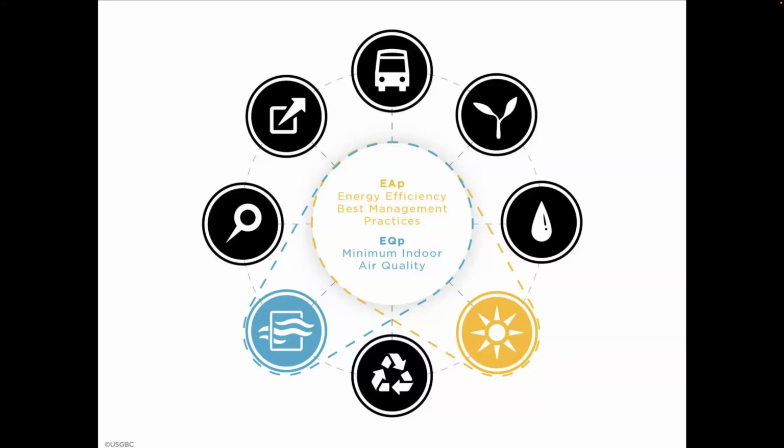So the filters you see in HVAC systems, whether in your home or elsewhere: the more stringent the filtration, the more energy it takes to push the air through that filter. If you use what's called MERV, it's an acronym, and you have really strong filters, it takes more energy to push air through them. So it's a balance between energy efficiency and air quality, unfortunately. So you may hear about that as well.